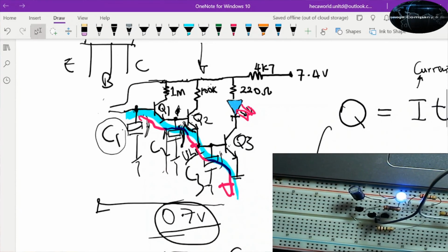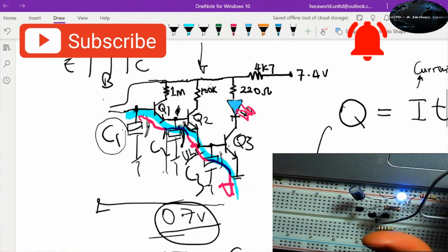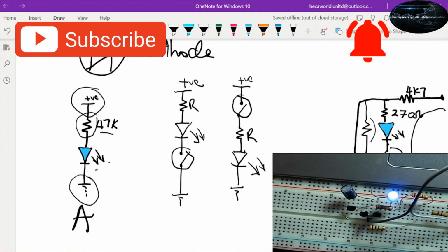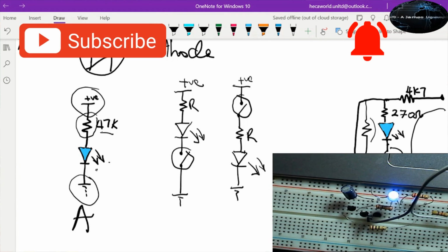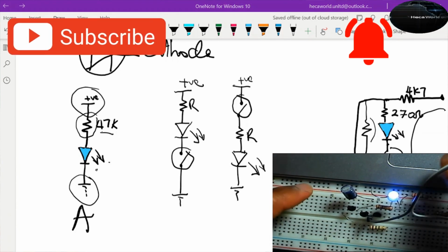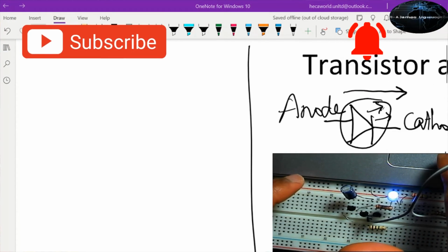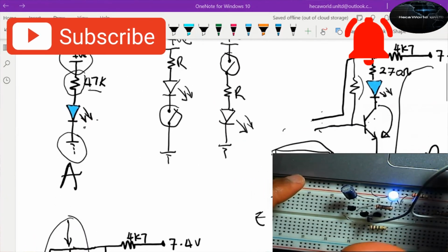Alright, and also if you just want to trigger something right away without a delay, then you might consider not using a capacitor at all. As I stated earlier on, this transistor will stay on until the capacitor is fully discharged, or discharges below 0.6 volts.